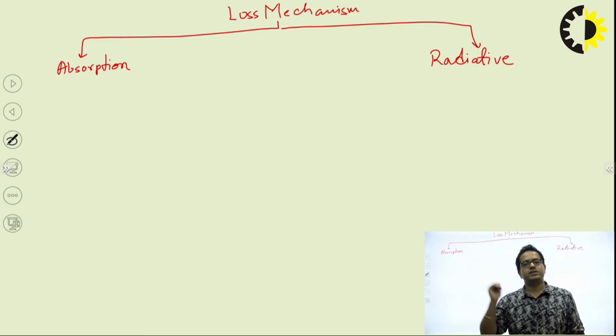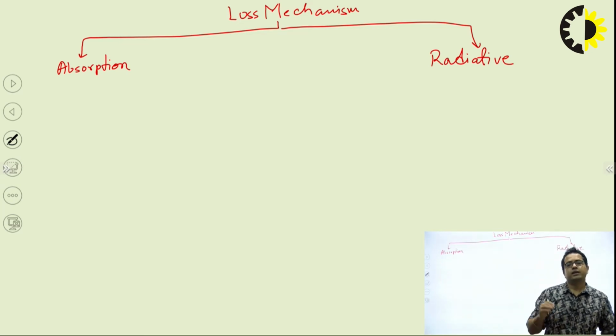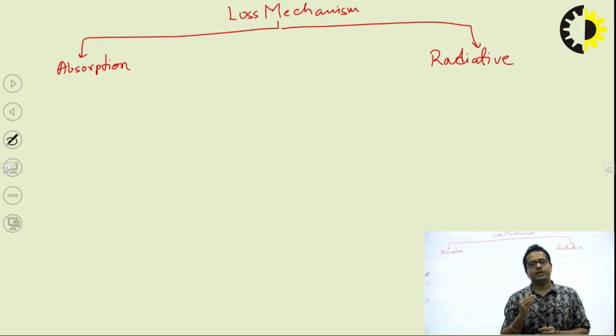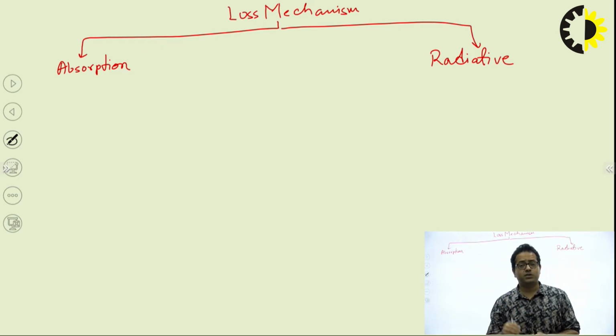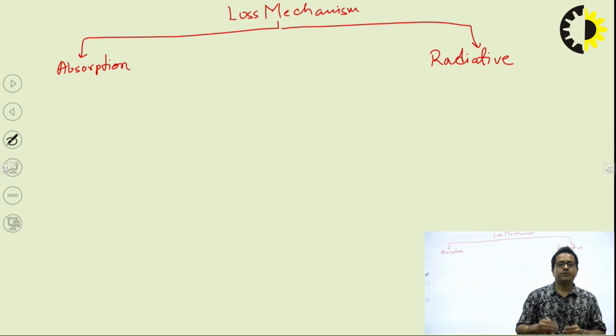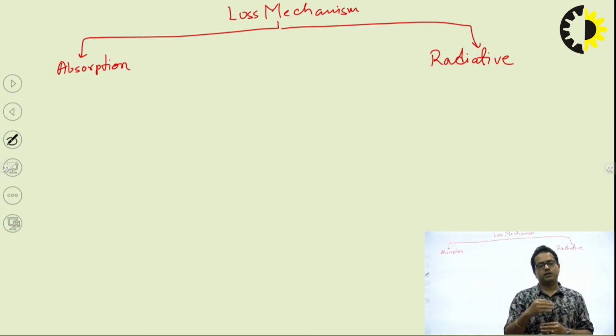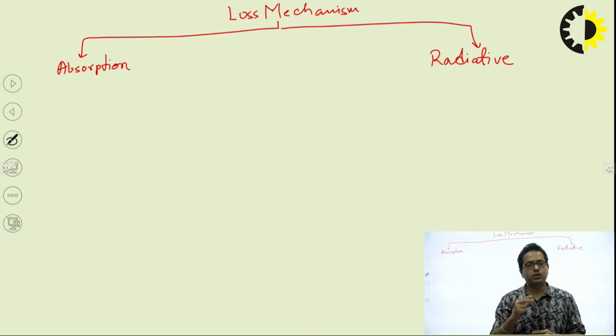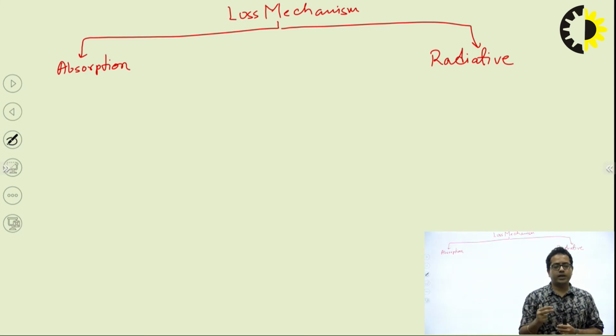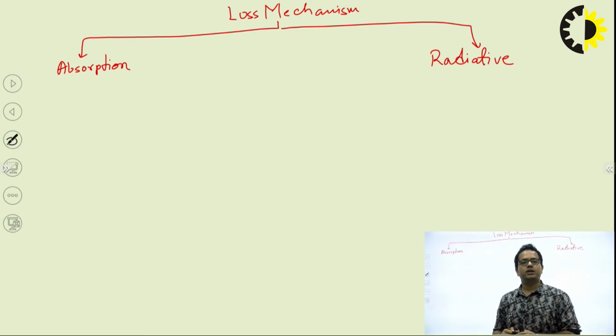Power gets coupled inside the clad, and we can get that power, but the strength will be very less, because the power that is traveling in the clad is going to decay exponentially, and we are considering the width of the clad to be such a value that whatever power is moving into the clad is going to decay completely before it reaches the end of the clad region.